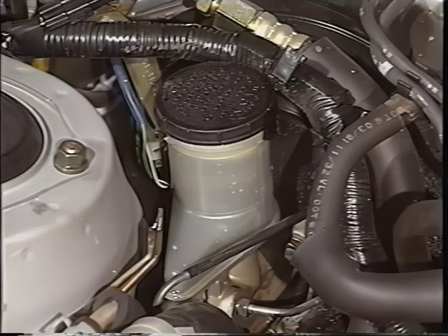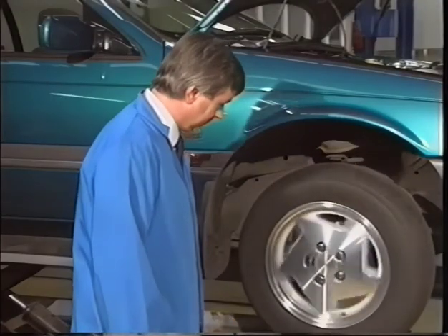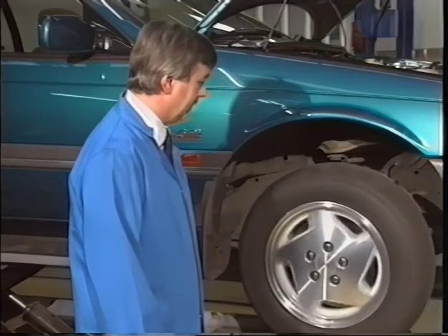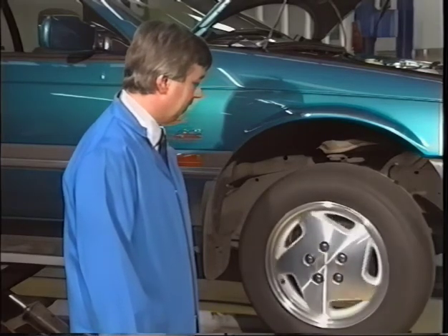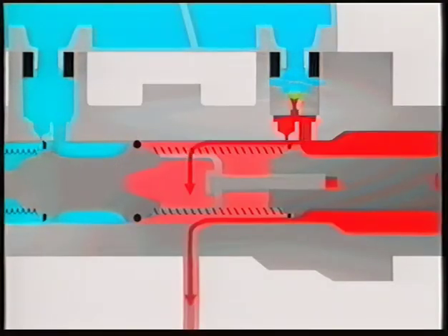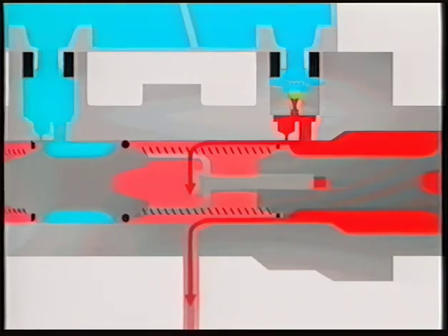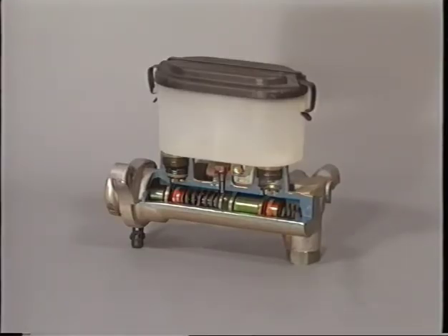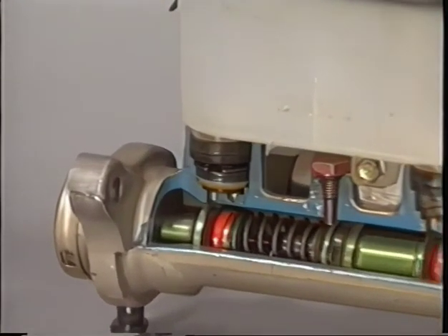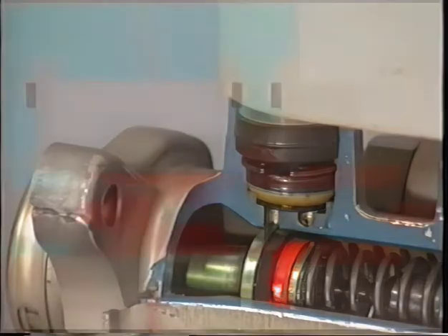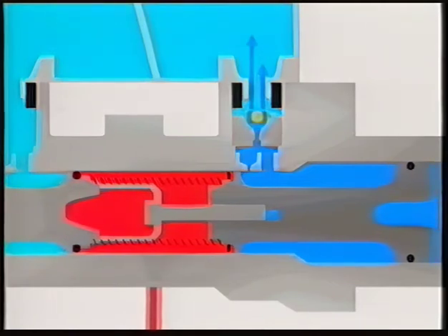The last component that we looked at was the master cylinder itself. It was seen that, in the interests of fuel economy, brake engineers are designing systems that have virtually no wheel drag. Because of this, fast-fill master cylinders having a stepped bore have been introduced to provide the increased fluid displacement these low-drag systems require. Fluid displacement is controlled by the fast-fill valve, which opens at a preset pressure and directs fluid from the large bore section back into the reservoir. If this valve should fail in the open position, the large bore would cease to be effective, resulting in low brake pedal.